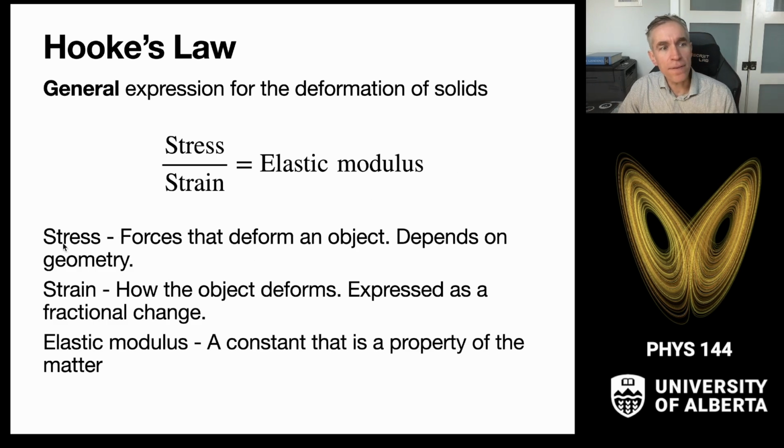To start off, stress is referring to the forces that are deforming an object. And this requires both an understanding of the forces that are pushing on the object and also the geometry, usually the area over which those forces are being applied. The strain is the resulting change in shape of that object. And this is almost always expressed as a fractional change. It can be a change in a length relative to another length, or we'll also deal with changes in volumes of objects. And it's always the change over the original volume.